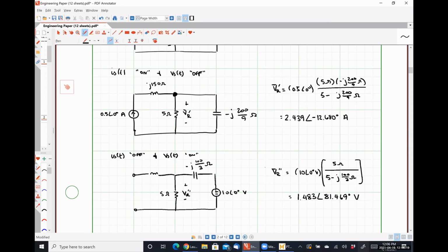They're not operating at the same frequency, so no. I can, however, add them in the time domain because then they're just simple sinusoidal signals, and I can add those together all day. That is a very common mistake, to just simply say, well, I'm using superposition, so I add this one and this one together and I get the answer. Can't do it here in a multi-frequency circuit. You have to go back to the time domain and then add the time domain results together.